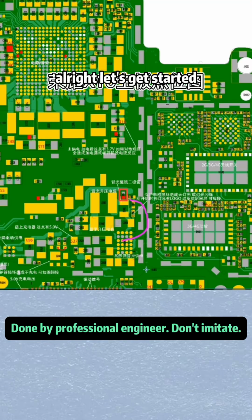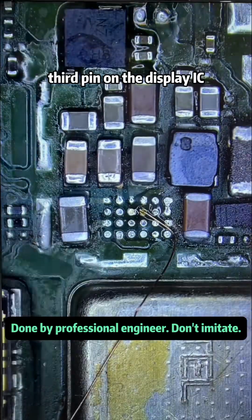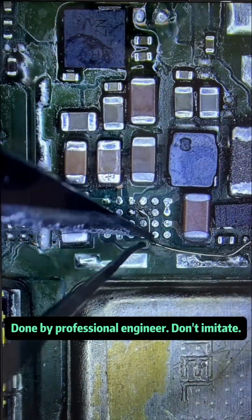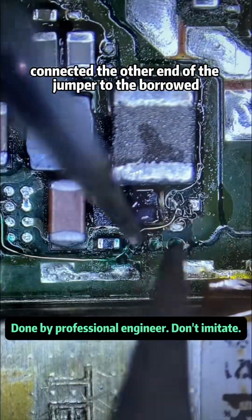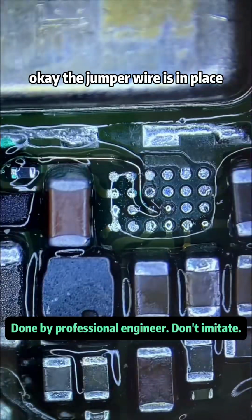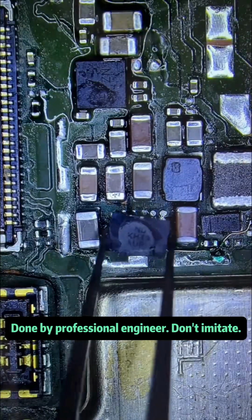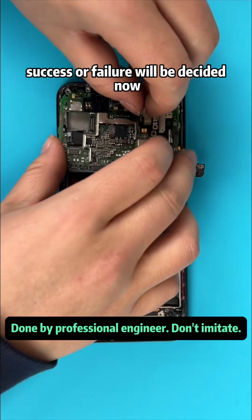Alright, let's get started. We cleaned the pad and connected a jumper wire from the disconnected third pin on the display IC. Secured it with green solder mask. Connected the other end of the jumper to the borrowed voltage point. Secured the jumper with green solder mask again. Okay, the jumper wire is in place. We reinstalled the display IC on the motherboard. Success or failure will be decided now.